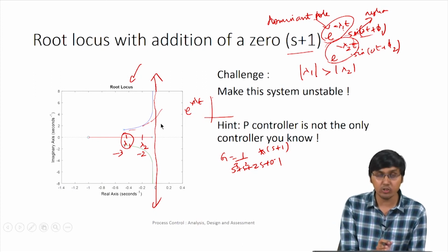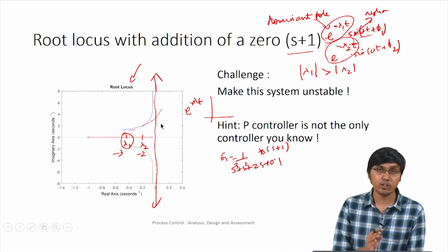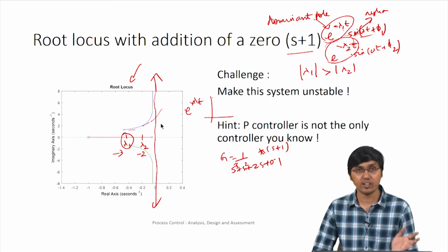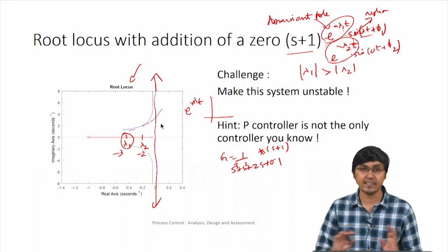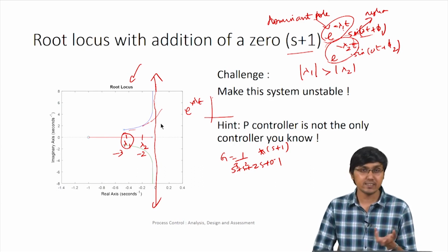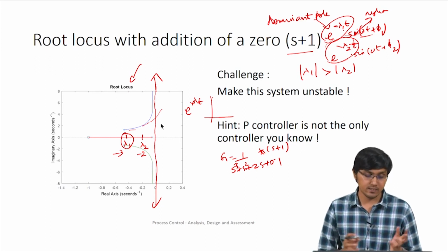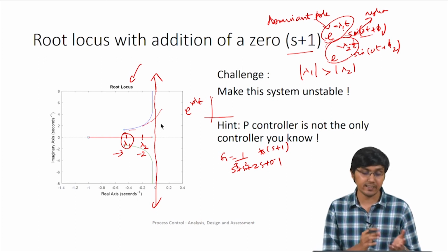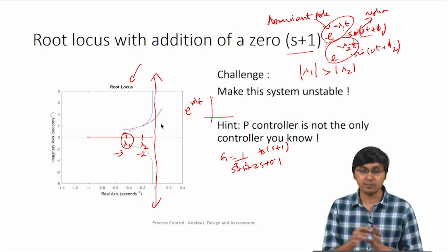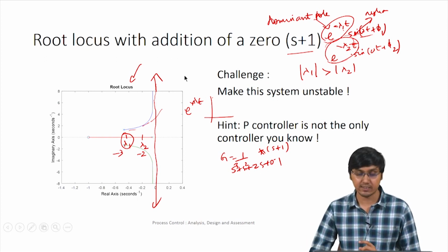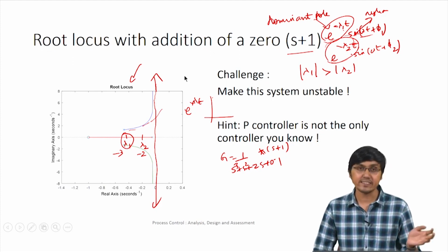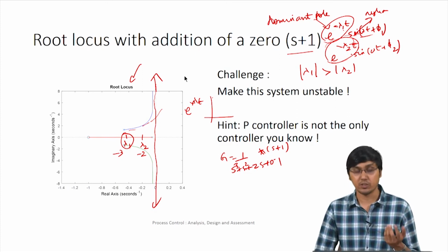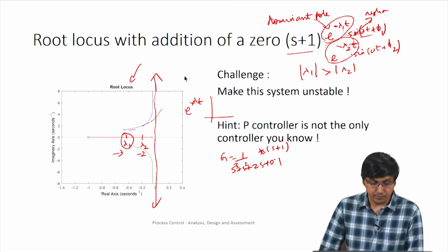The poles that are closer to the imaginary axis are going to have a bigger impact. So poles that are closer to the imaginary axis are called dominant poles. You can just remember these terms. You may hear someone talking about these terms, so you should not think this is something new. It's very easy to observe when we do the partial fraction expansion. If you want to understand it more, just take some lambda 1 value and lambda 2 value, and then see the response of the system. That is what you will be able to see.